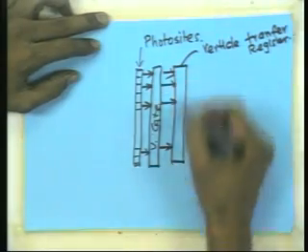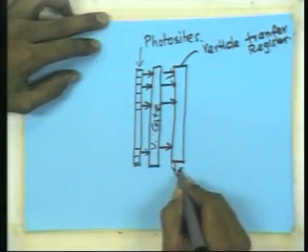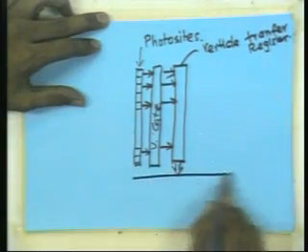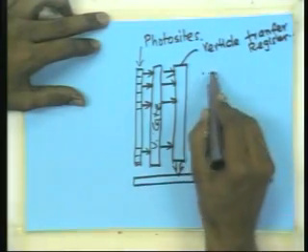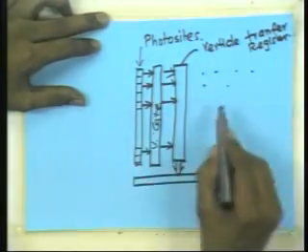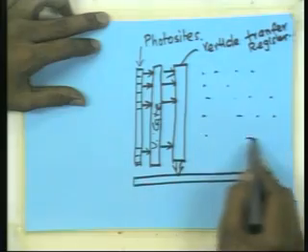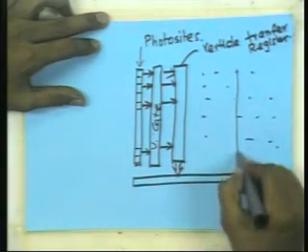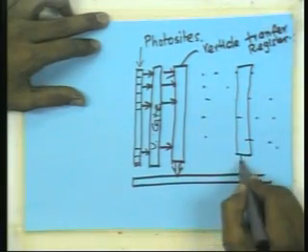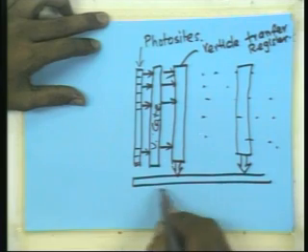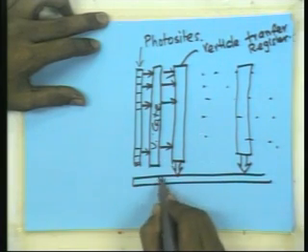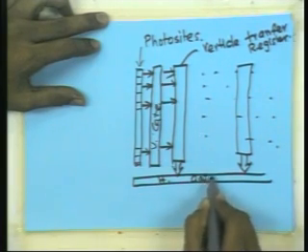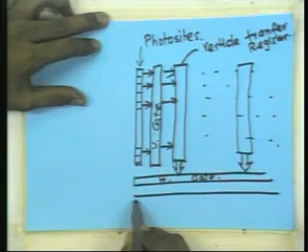Now, from this whole shift register you transfer it through another set of gates. So, these things are repeated here. What I have shown here is repeated along here, and each of these in turn, the voltages are again controlled so that they go through the horizontal gate into the horizontal shift register.